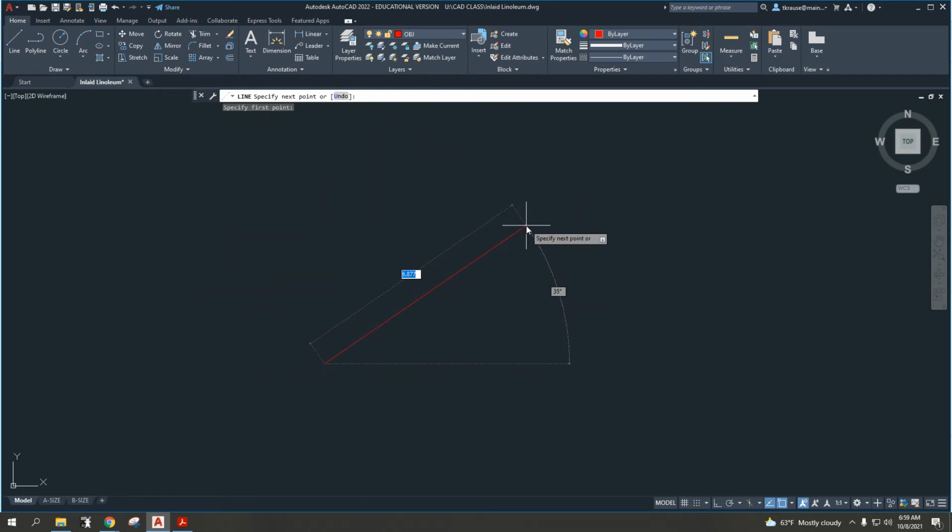Now, personally, I find there are some settings in the software that are quite useful to help us make sure we draw perfectly horizontal and perfectly vertical lines. That option is right down here, and it is called Ortho mode, okay? You can see it's also accessible with the F8 key on your keyboard. It is currently not turned on. If I hit the button with my left mouse, you'll see that it is currently highlighted. So what that immediately did is it restricts my lines to perfectly vertical or perfectly horizontal. Okay, another item, and I'm going to hit escape here.